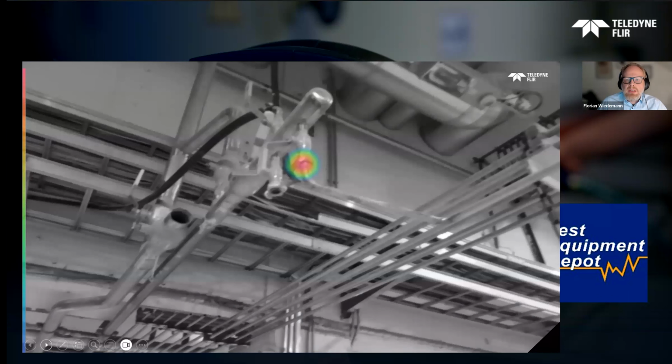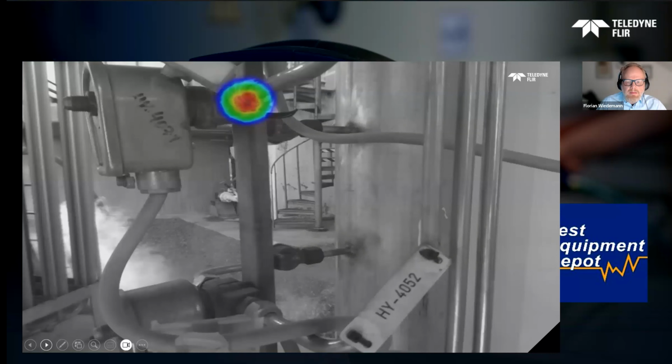Now we see some examples of typical images that were shot during a walk through a factory. So here, for example, we have one at a connector at this 90-degree angle. It is quite far away. When the production is running, you have noise around. You would never find this very easily. So here we have a leak from a bit longer distance, a bit far away. We should get closer and locate the source.